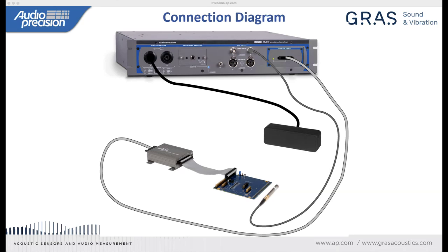Well, if it's a musical microphone and I want to say measure it all the way down to 20 hertz, I might need a different speaker, just something that has much better low frequency extension. And the same with the sound pressure level issue. For example, some microphones don't have an overload point until above 120 dBSPL, or maybe 140 dBSPL, depending on the microphone. So there you would have to make that selection again.